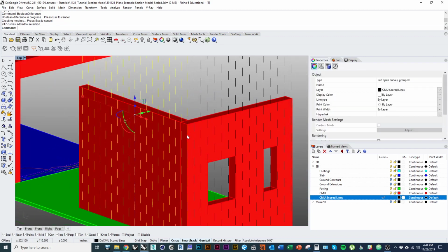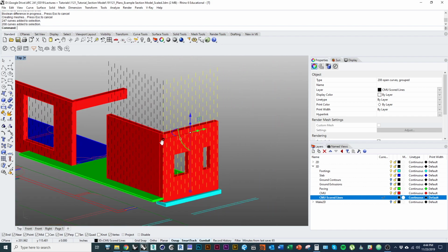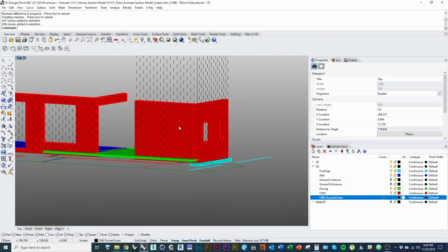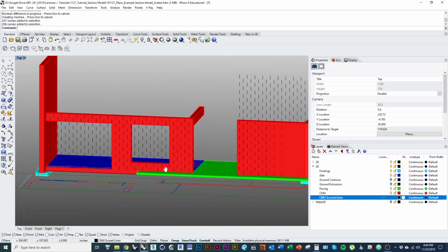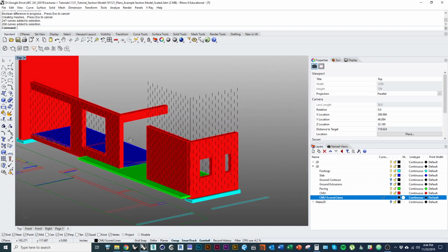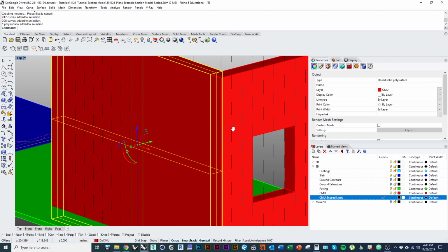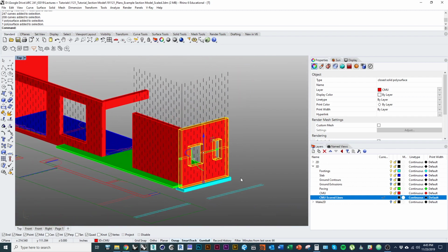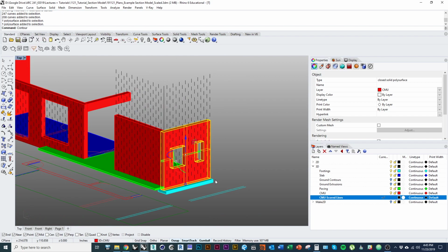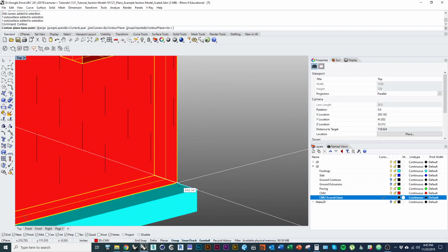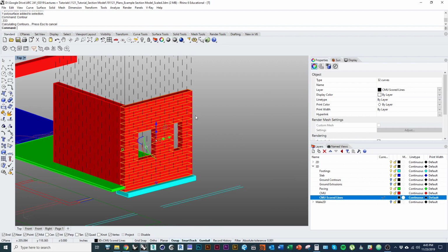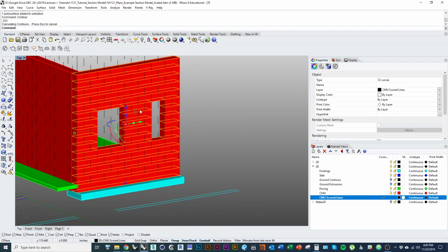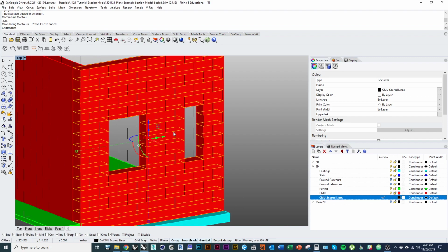And then, the reason I wanted to do this first is because now I could also draw my horizontal lines, but we'll do that basically just like what we did in drawing the ground plane. So I'm going to use the command contour. I'm going to start at the base of the wall, draw a line up that defines the direction of my contours, and the distance will be 0.333, 8 inches. There we go. And now those contours are going to wrap perfectly around where my windows are. So that saves me a little bit of work.